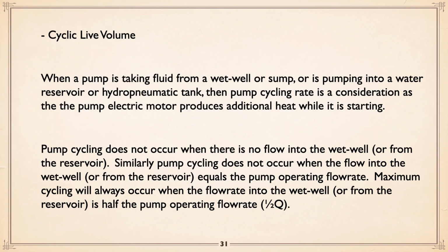Now, one of the things with pumps, very often you're operating in a cyclic situation, pumping out of a wet well or pumping into a reservoir or hydropneumatic tank, which is essentially a reservoir. Then you're turning the pump on and off based on the levels. Pump cycling does not occur if there's no flow into the wet well. Obviously, you don't have to worry about anything. Does not occur when the flow into a wet well or the reservoir equals the pump operating flow rate.